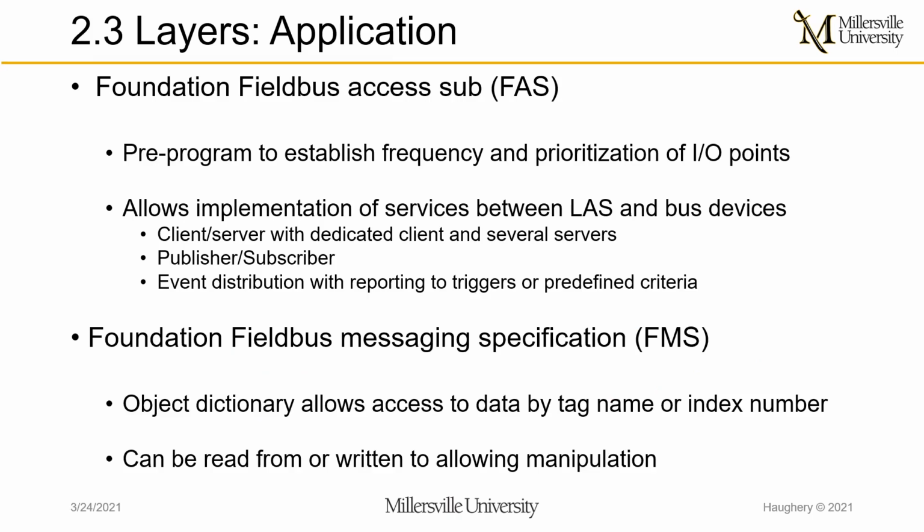How Fieldbus is used is to pre-program and establish frequencies and prioritizations of input-output points. It also allows implementation of services between that link active scheduler and devices on the bus for the Fieldbus network. For instance, you've got examples such as a client server with a dedicated client and many servers that it can connect to, or a publisher and a subscriber, or something needs to distribute events like warning events to trigger inputs and outputs on the bus for the Fieldbus network based on criteria that's already been set up by the user.